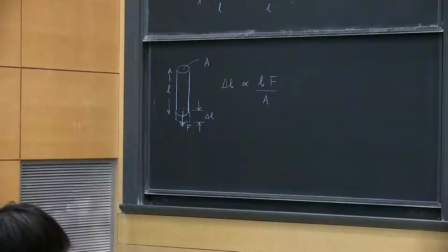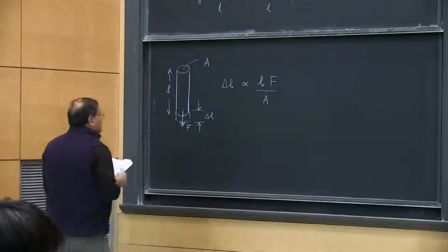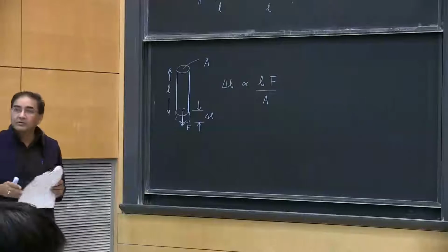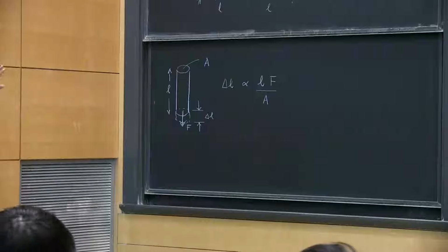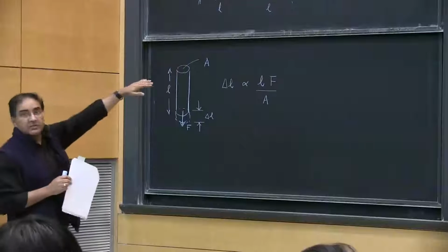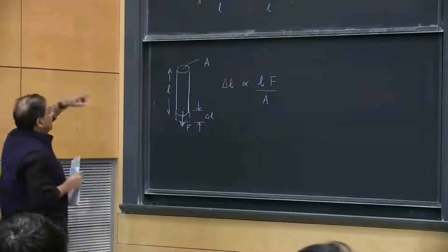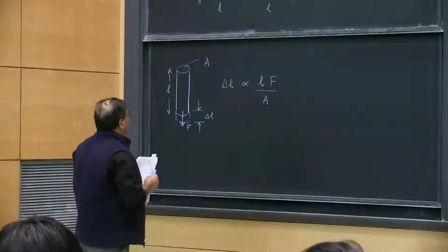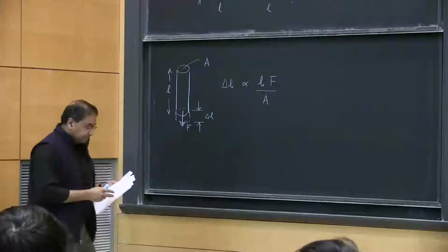So very simply put, I can draw up a proportionality like this, using what we call the joint proportionality theorem, in which delta L, we know separately, is directly proportional to the force. We know delta L is inversely proportional to the cross-section, because the number of springs ties with cross-section. And delta L is also directly proportional to how long the wire is. So if I combine them all, that's the joint proportionality theorem. You can write this down.